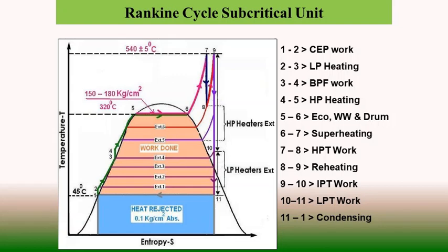Then there is further expansion in the LP turbine. During expansion in the LP turbine, we take 3 extractions: the first extraction goes to LP heater 3, then LP heater 2 and then LP heater 1.